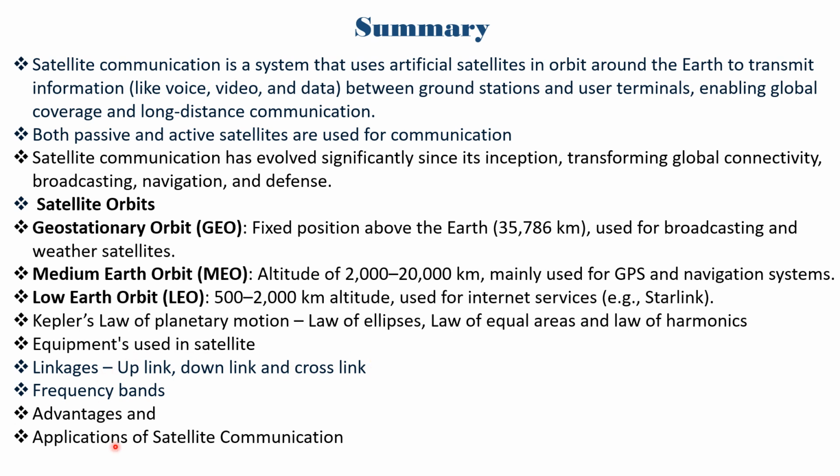And we also discussed the frequency bands, that is the assignable satellite frequencies, which can be used for military purposes only, or multi-mission terrestrial and telecommunications, and multi-band for telecommunications only, which may include maritime services at 1.5 gigahertz to 1.65 gigahertz for data and communications with ships at sea.